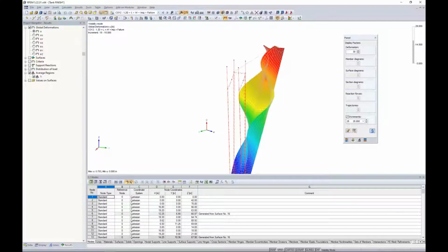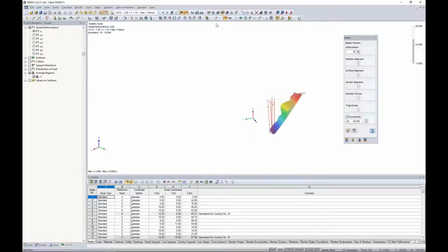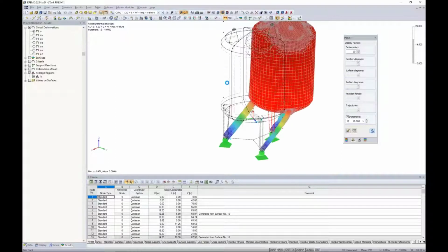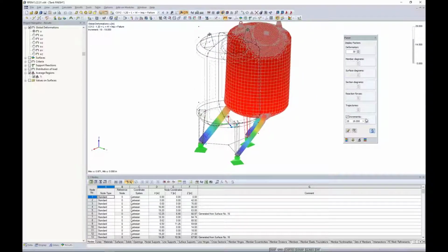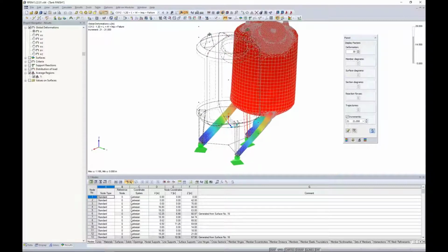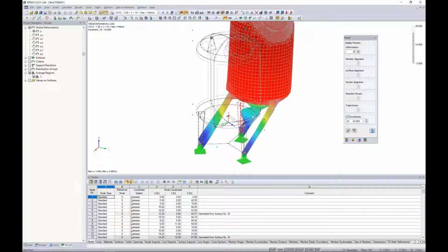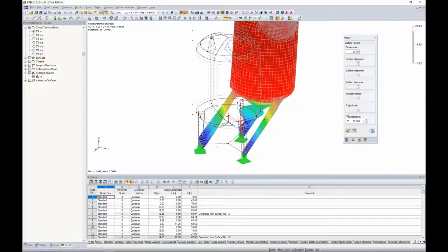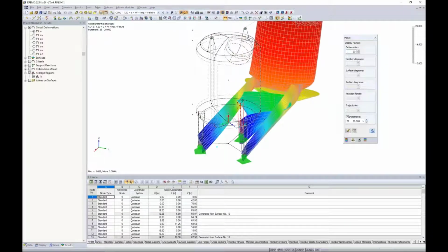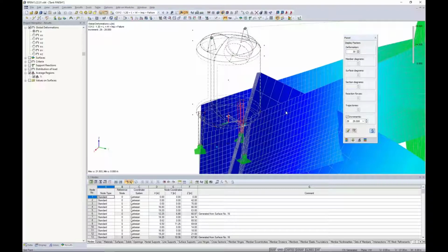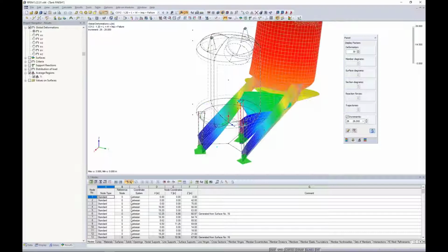Now I can activate the rest of my structure here graphically. So as we're reaching these higher load increments, the structure is still holding on. We're seeing very, very large deformations here. Of course, the deformation factor is set at 30, but obviously the leg is a problem until we get to a point that the program says, okay, I can't handle anymore. It's reached 29 load increments and the structure has completely failed. So we might be interested in the load increment 28 here, and we can even scale down our factor to 10 just to see moments right before the structure fails.